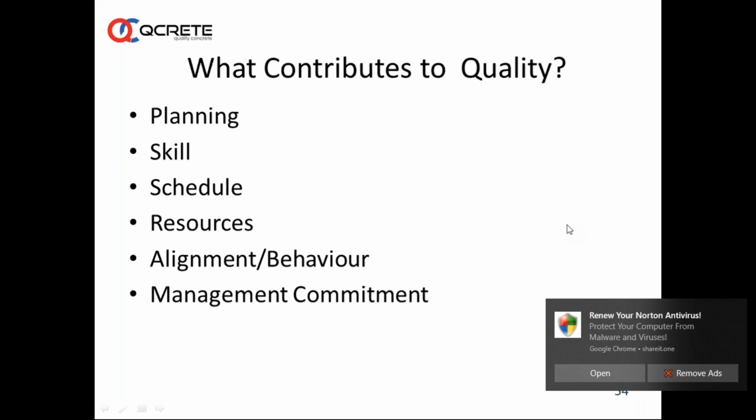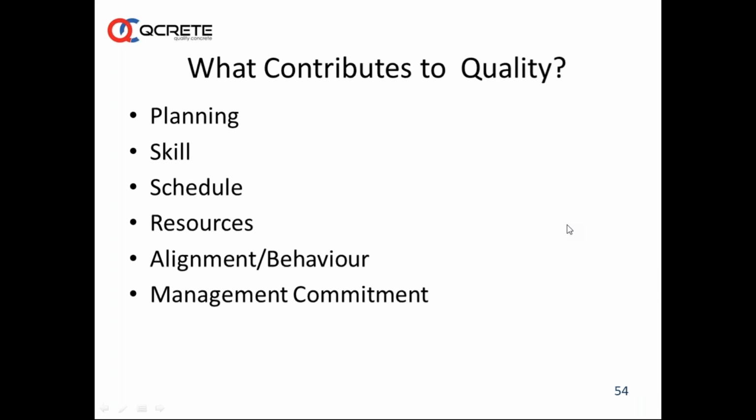Thanks a lot. How to minimize variation in the slump retention? Mr. Amarnath Pandey is asking this question. Slump variation, if we want to minimize, we need to have the same source of materials. Once we do the trial and set all these materials, we need to have the same source of materials. We should not change any of the ingredients at all.